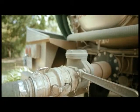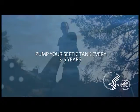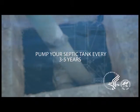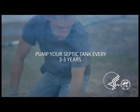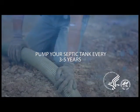The general guideline is to have your septic tank pumped every 3 to 5 years, but it really does depend on individual home usage and how selective you are as to what solid materials pass through your system. The wastewater that is between the 2 layers of solids is called effluent. The effluent is partially treated by anaerobic bacteria present in the tank, and it will continue to flow out of the tank through the next portion of the sewer system.